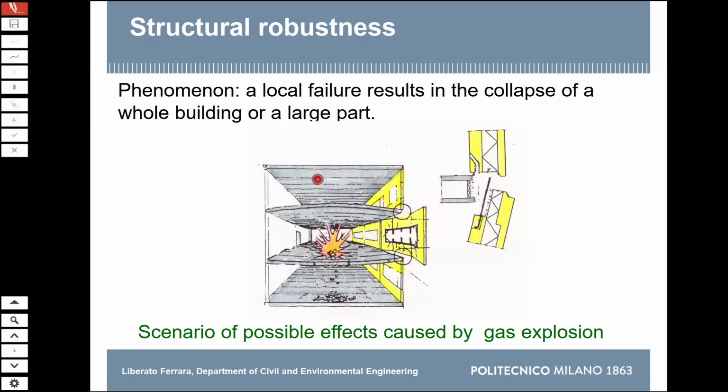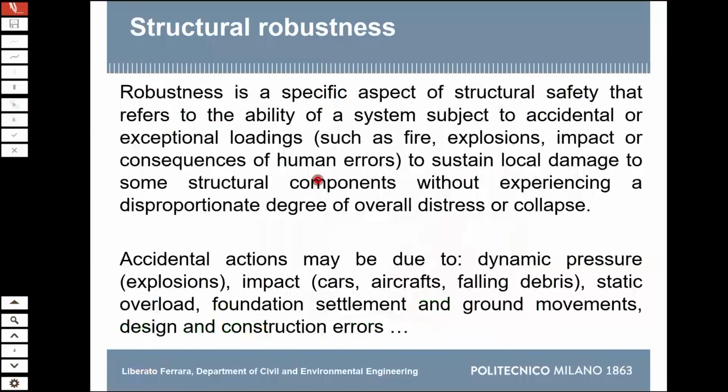And you had the blowout of the facade panel. But at that point, what happens? If this facade panel blows out, the floor on the top loses one support. So you had this block of 2-3 stories on top of the point where the explosion happened that started falling on the bottom floors, which were not designed for that, not only for the weight of the floors collapsing on them, but for dynamic amplification. And so you had the collapse over that.